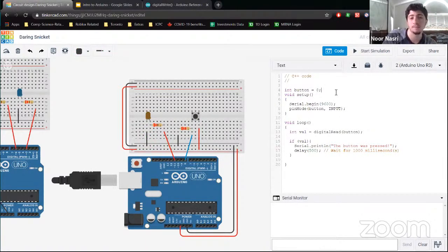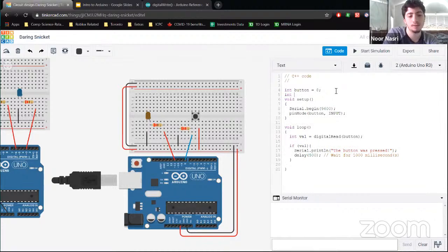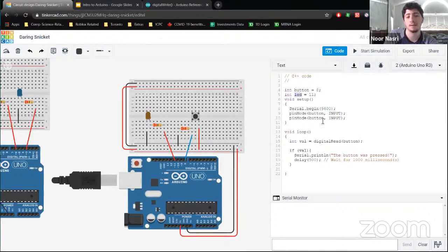So this I'm just going to do int LED, and that's going to be 11. We're going to combine the input and output now. We're just going to have LED as output. And then digital read, we sort of get it. If it's on, we're going to turn. And this is just the else statement.